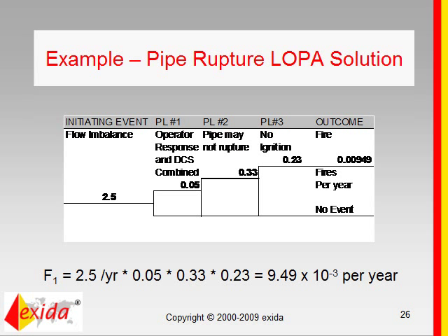In the majority of cases, people will actually use order of magnitude estimates for the probability of failure for different protection layers, and basically say, okay, this protection layer will give me an order of magnitude risk reduction or 2 orders of magnitude risk reduction. There is some judgment involved. Ideally, you have some plant history, for example, on your relief valves, indicating a certain probability of failure on those relief valves.